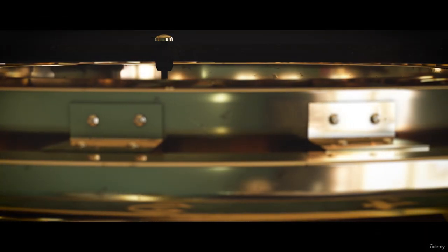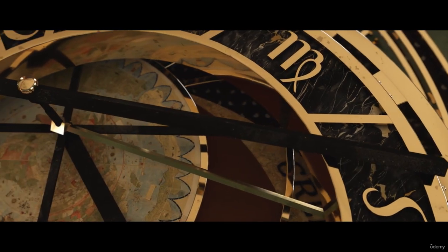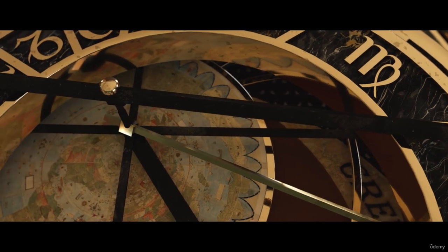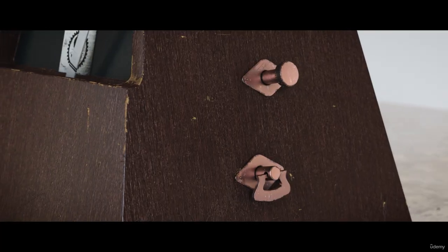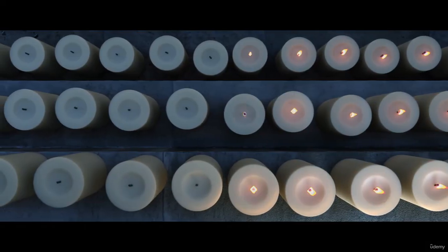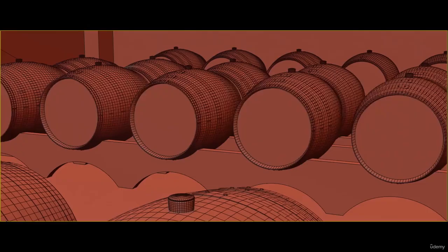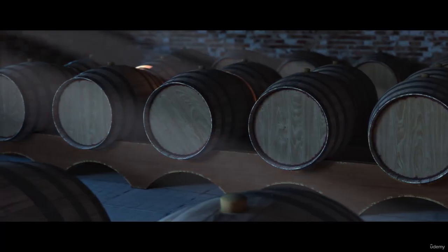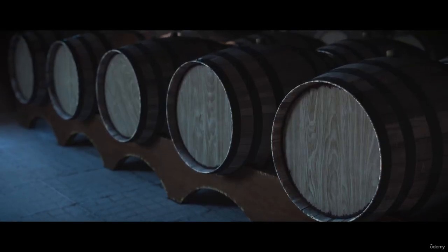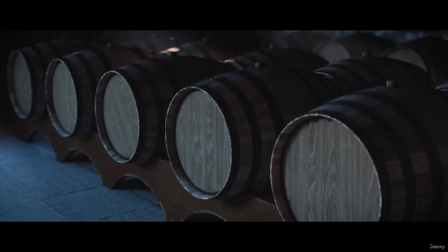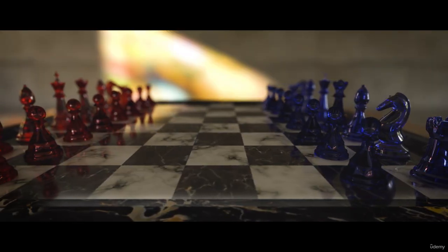All right, that brings us to the end of Lesson 6. Today, we explored the power of the modifier stack and learned how different modifiers can completely transform a basic object into something dynamic and visually striking. From stretch and twist to FFD and Boolean operations, we saw how modifiers give us the flexibility to create both mechanical and organic forms. We also covered the symmetry and sweep modifiers, both of which can save you tons of time and open up creative possibilities.